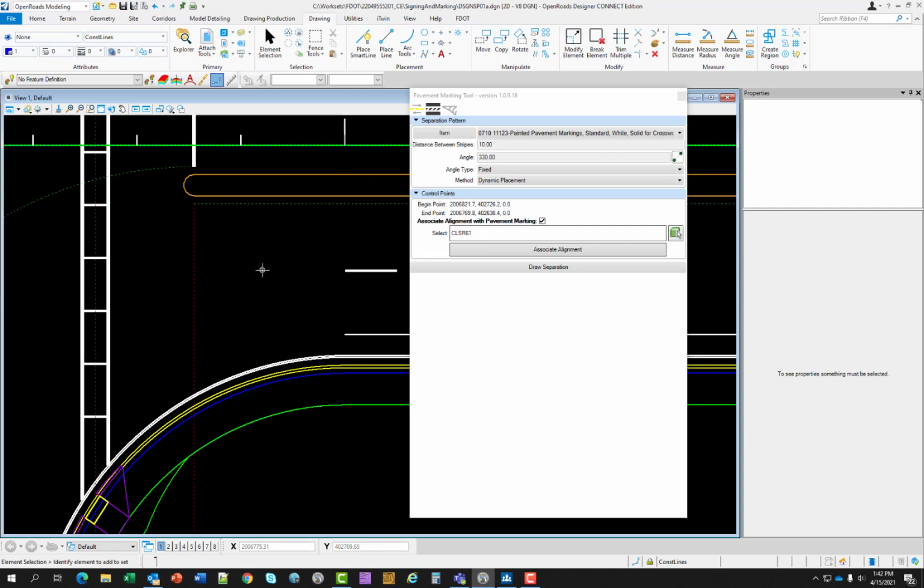And what we're going to do is extend these patterns to this red dashed construction line. And if your file does not have one, it's easy to just copy an adjacent construction line and move it here. It's at the end point of that green dashed construction line. Okay, so going up to the top here, trim to intersection. I'm going to left click on that.